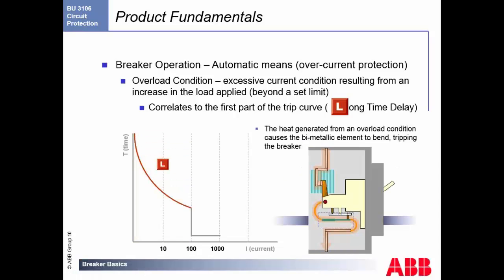How does this work? Well, what we have is called a bimetallic element placed into the breaker. This has two different metal alloys in it, a very proprietary combination. We can't tell you. We have to make sure that you sign an NDA. Basically, one of the metals will expand quicker than the other. This causes a deflection in the element. That element bends, and you will see that it trips. Again, if you look, the heat is heating up those bimetallic elements right down here in the box. As they get hot, they bend and open the moving contact, therefore disconnecting power down the stream.